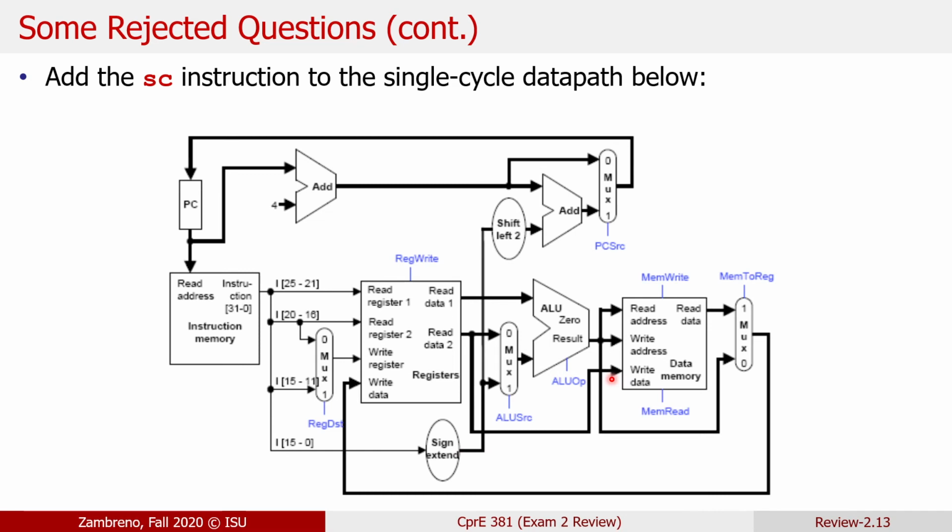I said in class just now it was store into the register file, in which there's not a direct path, but there's an indirect path, right? We can take our immediate offset, sign extend it, and maybe just add 0 to it. And then we have that value that we can connect back into the register file. So if it's write constant instead of store constant, that would be supported without any additional muxes.